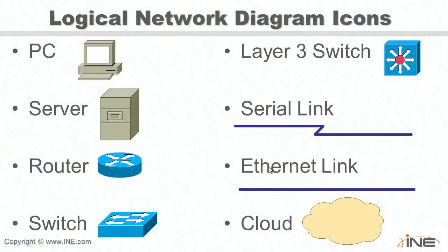Do you differentiate between fiber optic or copper interconnections? You can. A lot of this really depends on your own type of naming convention. So if you were creating your own set of documentation, usually you would want to. Because let's say you're running Ethernet over a copper cable versus a fiber cable, there's going to be a difference in how those behave and how you would want to troubleshoot it. So a lot of times someone will use a different color coding for the copper cables versus the fiber cables. So there's not really any hard and fast rules. It's just, when you look at the diagram, does it make sense to you?